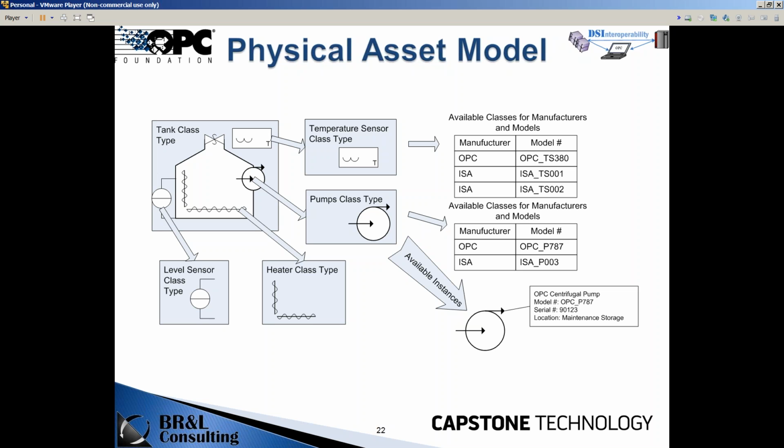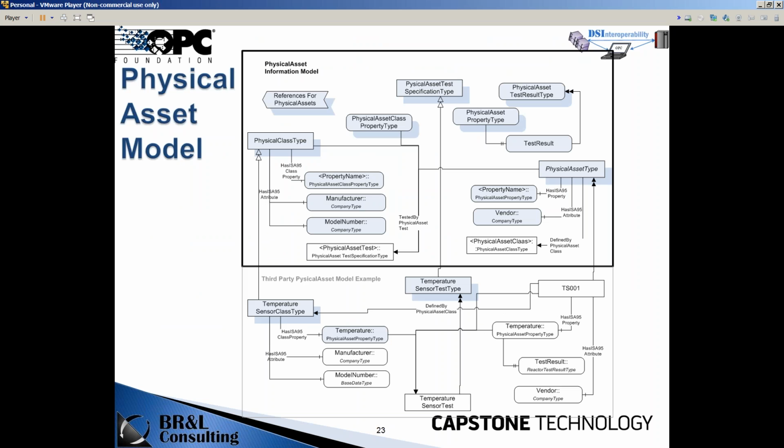There's the physical model and the role-based equipment. So if I'm looking back at a pressure, I don't care which sensor provided the pressure. I just want to see the pressure. So that equipment stays the same throughout the life of the process. The physical asset, though, maybe has to be taken out for maintenance. Maybe it's put back in a different place in the plant. And sometimes it's worthwhile to track that because maybe that physical asset has an issue, and you can determine it from the fact that, hey, every time I put this in the plant, it lasts 3 weeks, then I need to go perform some maintenance on it. So the key thing here is that there are two different models, and they're very useful together.